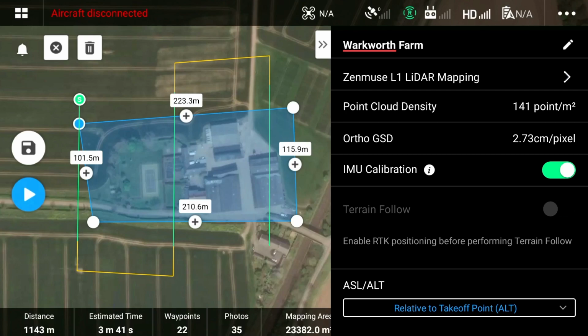Although the GSD parameter will always be present, it is important to note that RGB colouring needs to be switched on in order to capture RGB images. Again, we will show you where to find this soon. Photogrammetric ortho GSD is directly affected by one main parameter in your flight settings, and that will be flight height. If the lens was interchangeable or the camera held a zoom lens, then this would also affect the GSD. But in the case of the L1 sensor, the lens is fixed.